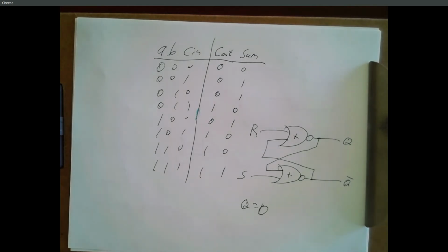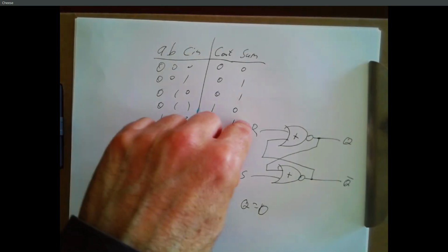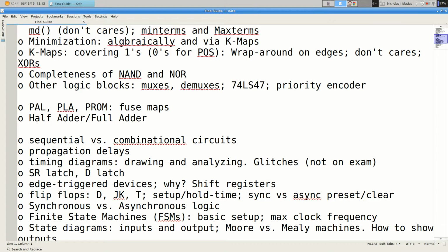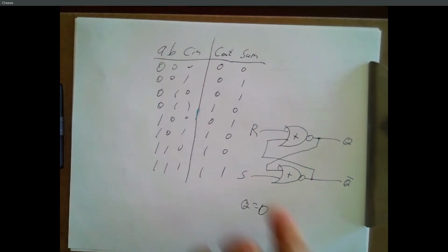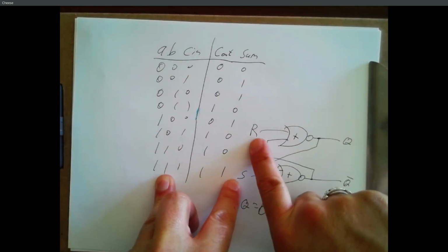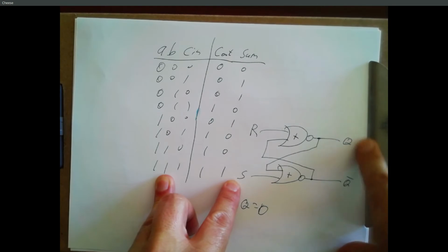But like I say, we didn't use these. We used this to build a D latch. Right, so have a D input and a load line that drives either the set or the reset line. But then we turn those into flip-flops. And flip-flops, the big deal with flip-flops is they're edge-triggered devices, right? This latch acts based on the value of S and R, right? Anytime S changes, something happens to the outputs.